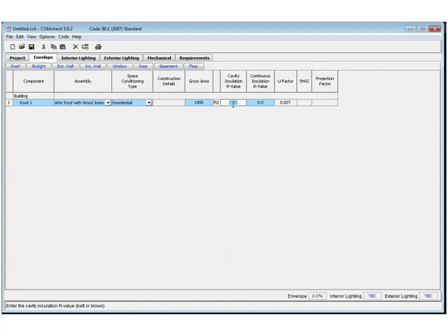If the insulation here, this R38, the software will make a couple assumptions here based on that R value of how many inches are above the trusses where there is no thermal break, and it'll run that calculation. Makes another assumption here, or calculation on this assembly type, of insulation decreased at the eaves for this one. Now if I chose a different roof type in here, calculation might be different, such as an insulation entirely above the roof deck.